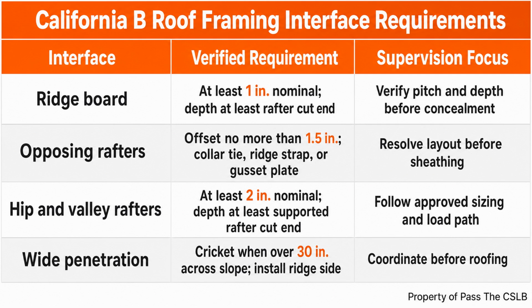I do not describe that as permission to ignore the shingle manufacturer's listing or the approved project details. The code baseline, product instructions, and plans all have to agree. At 4 and 12 and steeper, the special low-slope double application is no longer required by the asphalt shingle provision covered here. Wood shingles and wood shakes have a different minimum. They require at least 3 and 12. I keep material rules separate because a slope that accepts one roof covering may not accept another.